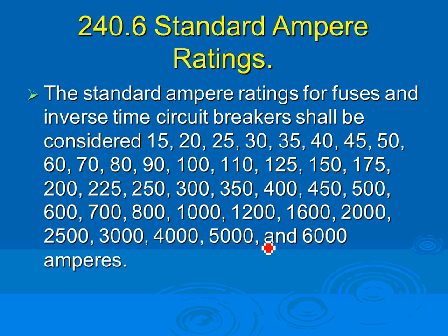So on a 1,000 amp service, under a rainy day, it could be 300 amps, between 300 and 700 amps, if you're pulling a lot and have a lot of equipment. So, long story short, we grossly oversize, especially at the level of the service.